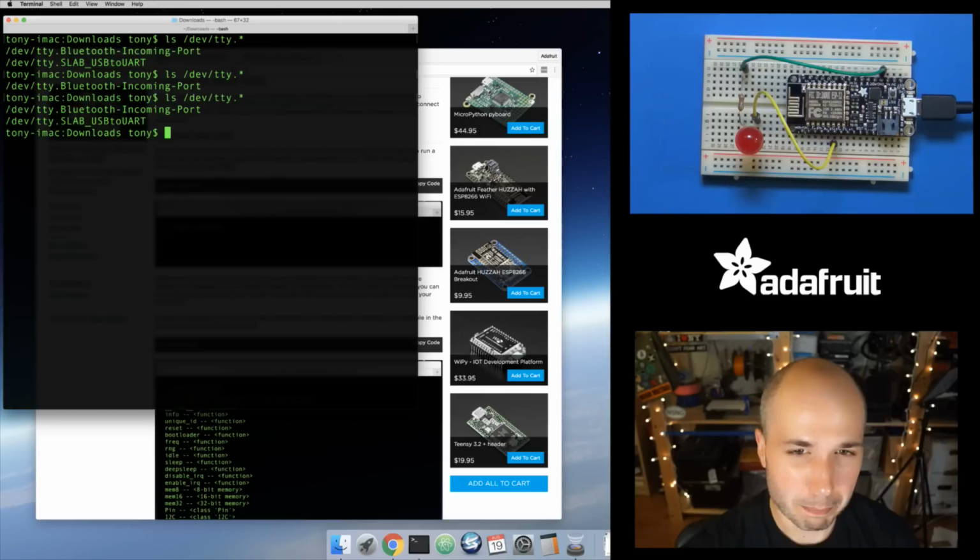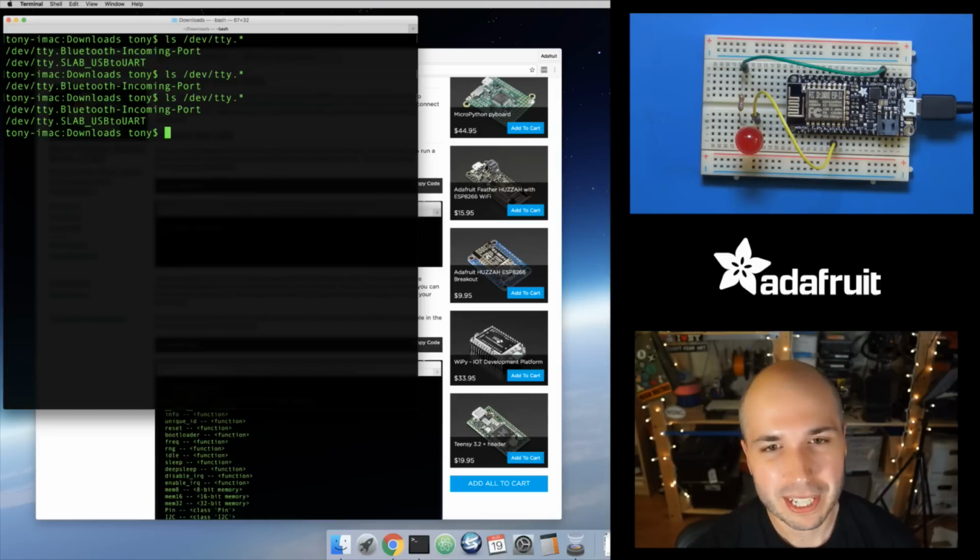There's a list of COM ports, and you'll see for this board at least there's a Silicon Labs node under there. So look for that and then look for the COM port number. Usually COM4 I think is kind of the default one that it gets, but it might be different depending on how many serial devices you have. So that's how you find that on your different operating systems.